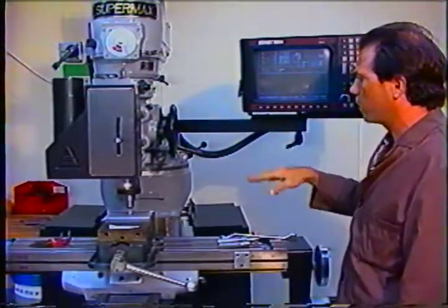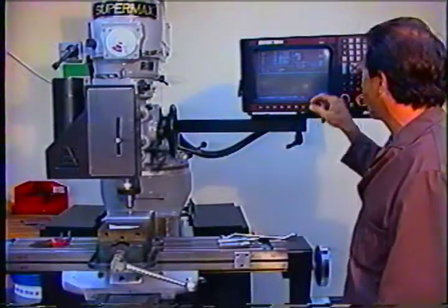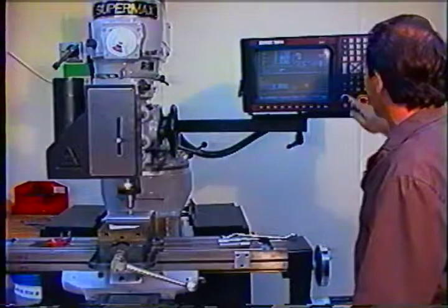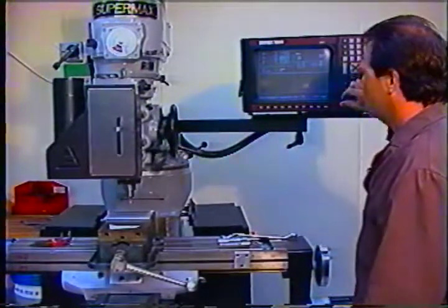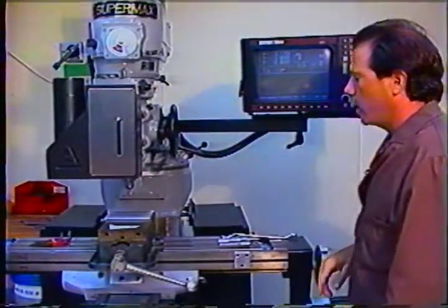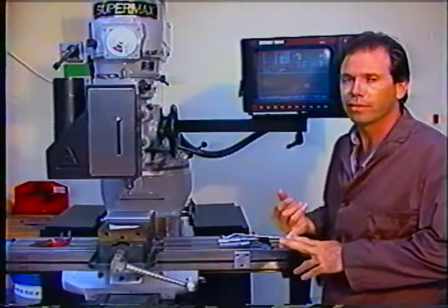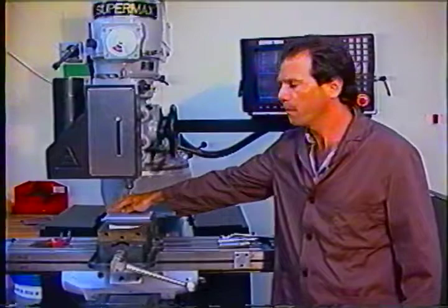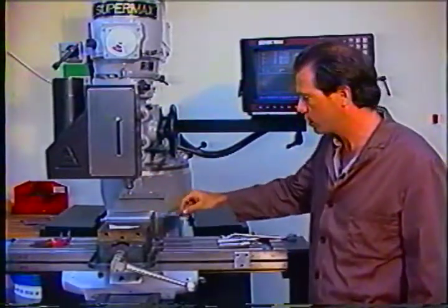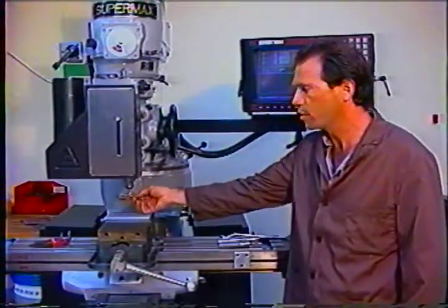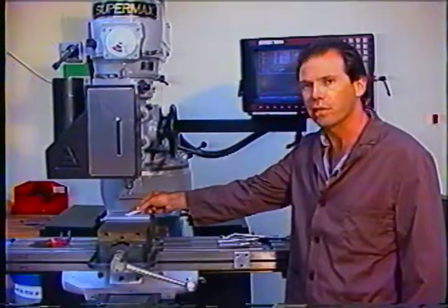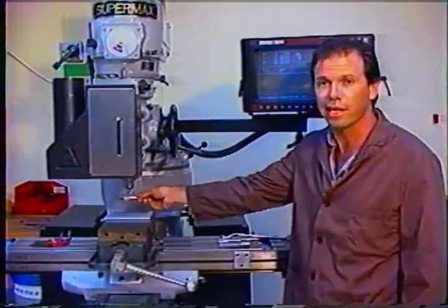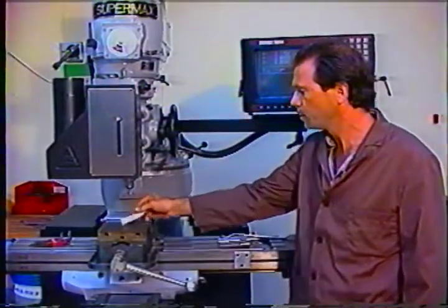One last step, I'm going to raise this tool back up to the home position by ensuring that my jog status is rapid and pressing Z0 start. Okay, that completes our setup of doing absolute 0 for X0, Y0 here on the corner of the part, and for doing our tool length offsets, which remember is the distance from the bottom of the tool to the top of the workpiece with any particular tool that you're using. The control holds up to 99 tool offsets, so there's plenty available.